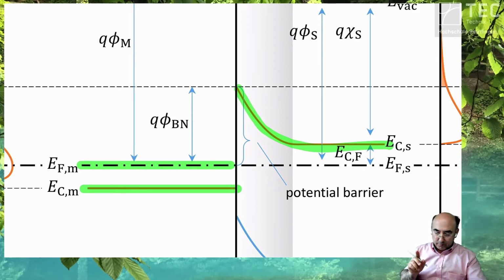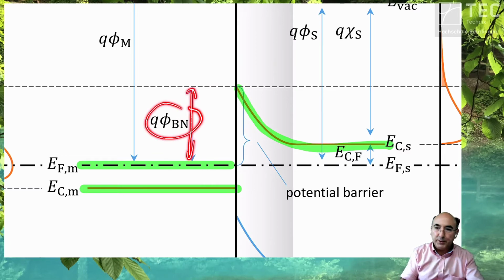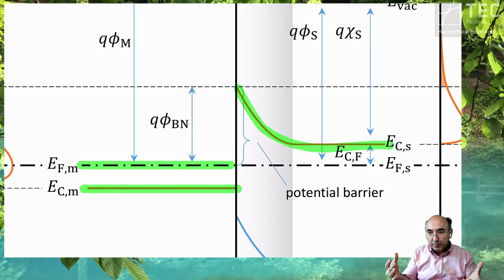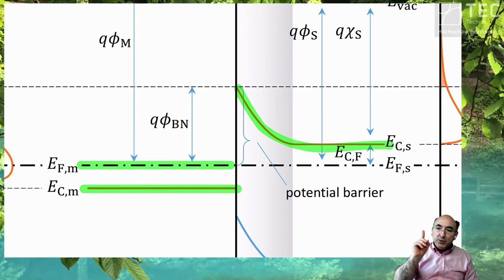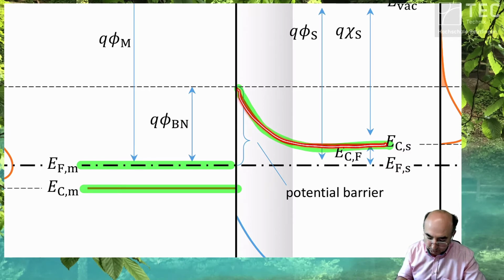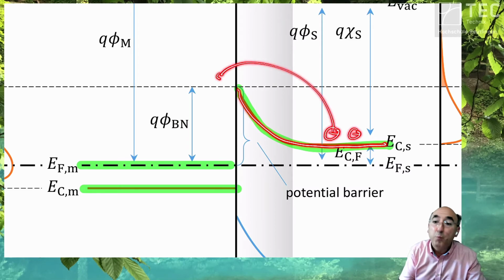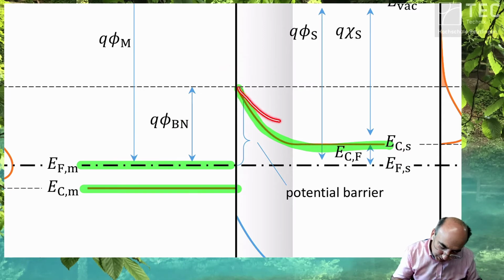What do you need for the electrons which are here as a dust to go here? They have to overcome this Schottky barrier. Okay, what happens if you heat up? This amount of electrons increases. What you need for the semiconductor to release its electron dust to here more than in the equilibrium, you have to change this bending.